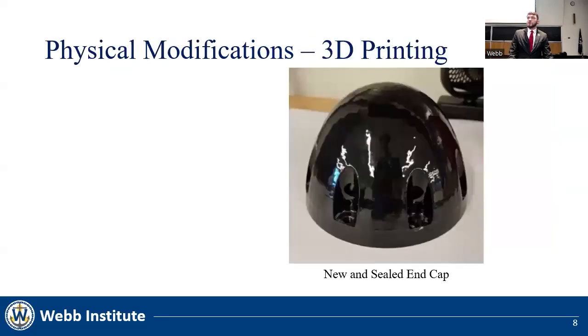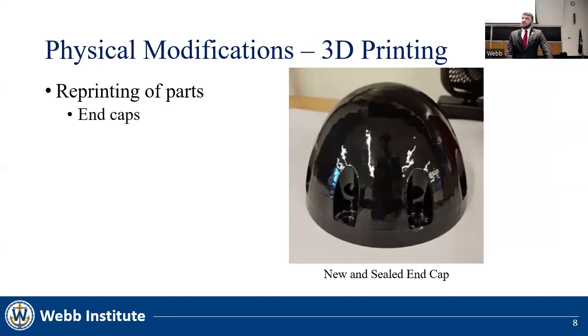Following up on the past work, we fulfilled some recommendations. First, we addressed the porous end cap problem. Previously, because of the porous nature of the end caps, water slowly leaked into the end caps, which affected the weight balance of the glider. To battle this, new end caps were printed and sealant was applied to prevent the leaks. One of the new end caps can be seen in the figure to the right.